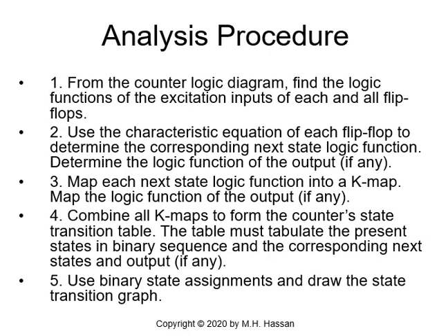So what we do is really the opposite of the design. From the counter logic diagram, from the given diagram, I will find the logic functions of the excitation input of each and all flip-flops. Use the characteristic equation of each flip-flop to determine the corresponding next state logic function, which is A plus, B plus, C plus.